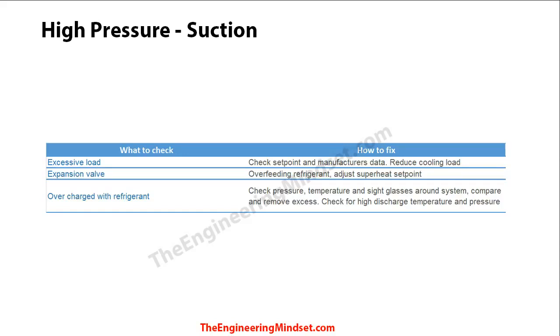And it's also quite likely that the expansion valve is overfeeding refrigerant as it's starting to break down. So you want to check this as well. If this happens, then you probably have to replace the expansion valve. But obviously do try to adjust the superheat set point first.